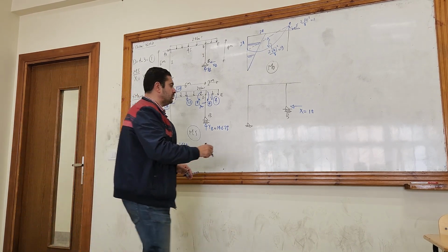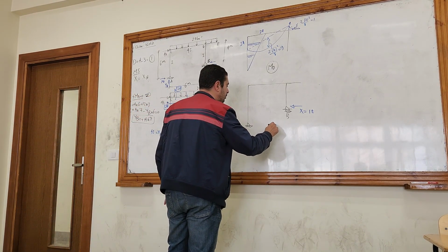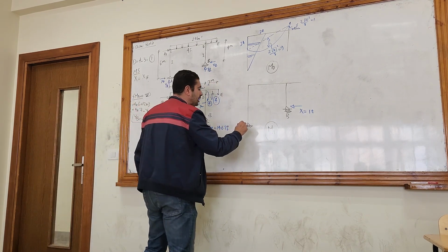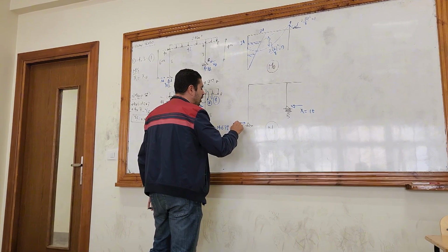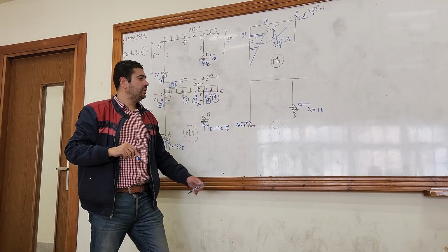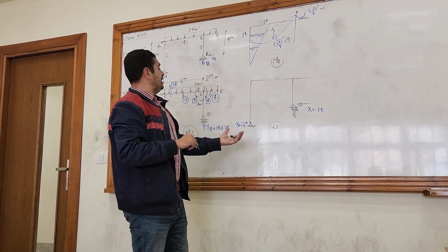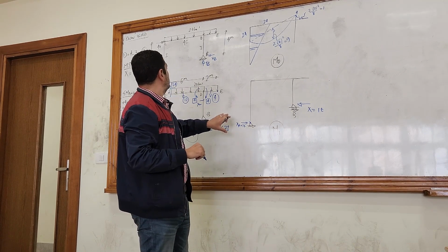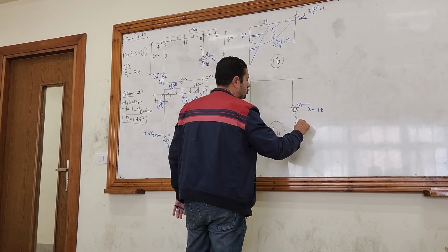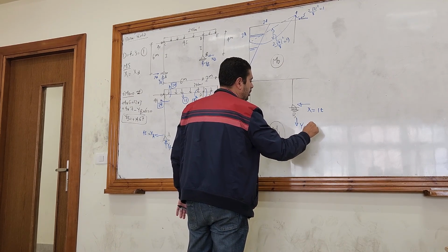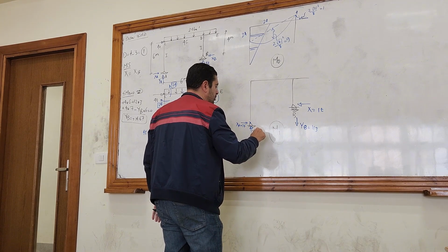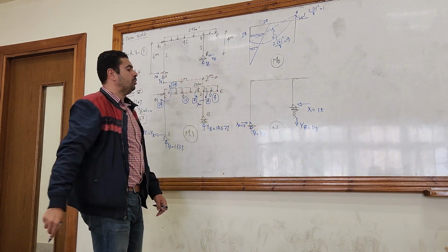What will be the moment called? It will be M1, right? Let's calculate the reactions. So here at A, XA will be equal to 1 in the opposite direction. Take moment here at A. So YD times 6 and 1 times 2. So 2 over 6 downwards. So YD is 1 over 3 and YA will be upwards in the opposite direction, 1 over 3.